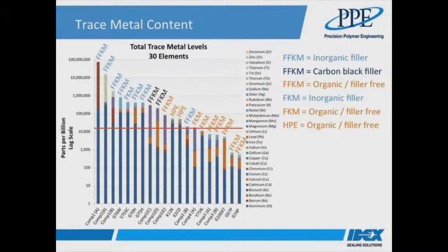Right, so we've seen all that good plasma erosion data and the relative performance of the different materials. We've just seen what elastomers can look like after they've been directly exposed to these plasma environments, which all tells us that small amounts of elastomer compounds in critical tool locations, such as, but not limited to, chamber lids and analysis port locations. So these bits of elastomer are going to end up drifting around the process chamber and potentially landing or condensing on the surface of the wafer.